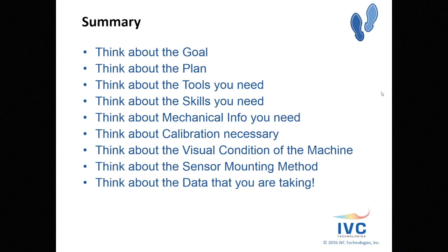So, in summary, think about the goal. What am I trying to accomplish? Once I've figured out the goal for my vibration test, then come up with the plan. What tools are you going to need to successfully carry that out? Also, what skills do the personnel require to be able to successfully execute the test? Think about some of the mechanical information that you may need for the analysis part. Before you actually get to the test, it may be prudent to contact some of the OEMs and start getting that information ahead of time.